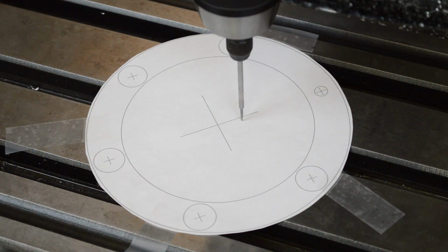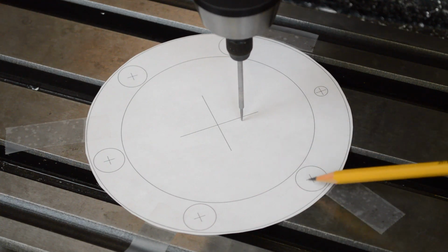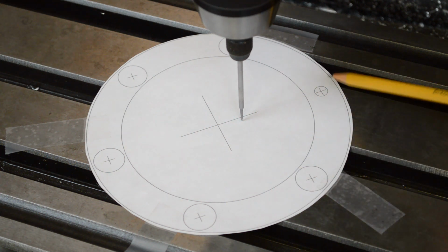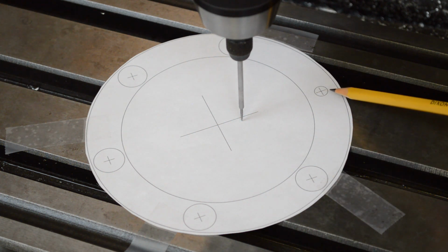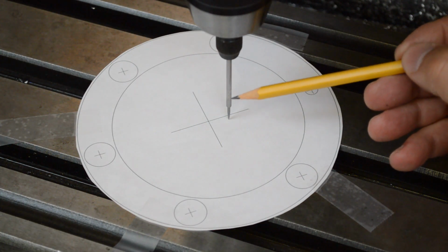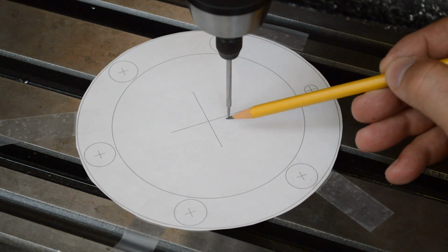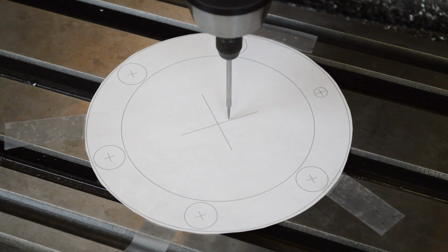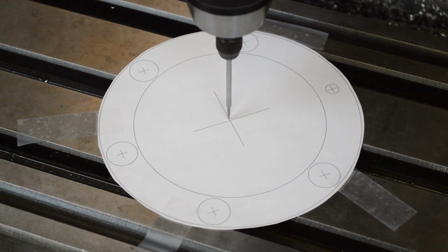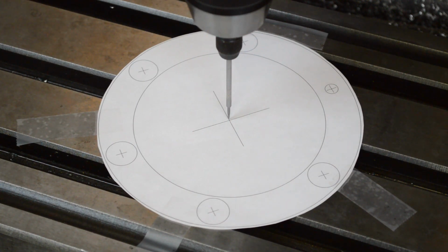Okay, so suppose this is our setup, and we only really know two things about it. We can figure out the center of this pattern, right? We can indicate the part somehow and find the center. And we have, say, one good hole, this one here. Alright, so what can we do? I'm just going to be using this pointer here in order to illustrate what I'm doing here. So the first thing we would need to do is indicate the part somehow to find the center of this pattern here. Okay, so we would indicate that hole and get that exactly on center.